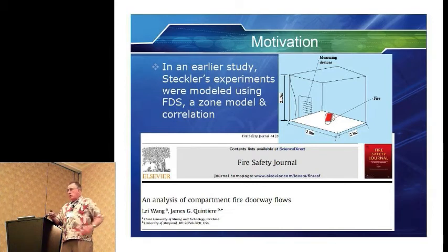The original theory was put out by Kawagoe for fully developed fires that have a uniform temperature inside, but early fires don't have that. So we know that there's a layer. And these experiments used very good instrumentation. We used the bidirectional probe in a doorway. The burner itself was a circular burner, and it was fit flush on the floor. So it wasn't raised, there wasn't any tripping over it. The floor was raised, and the burner sat on the floor.